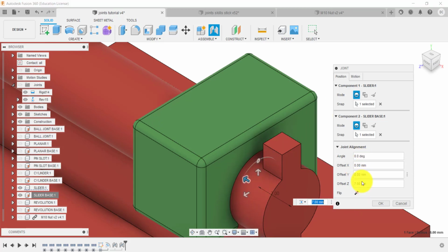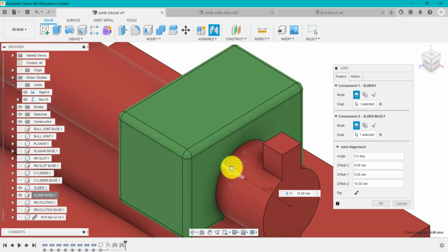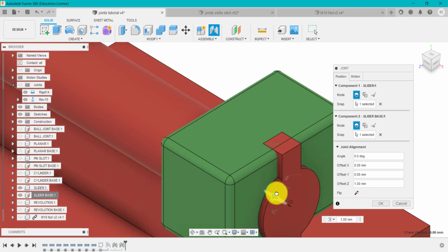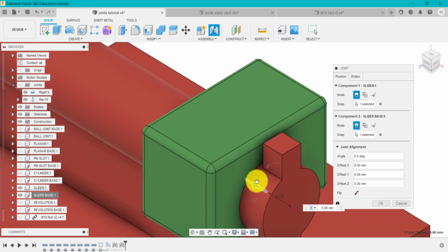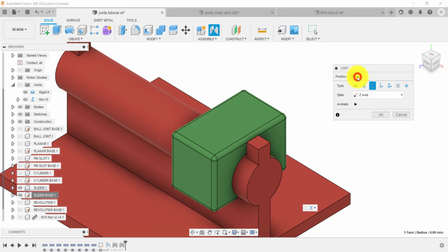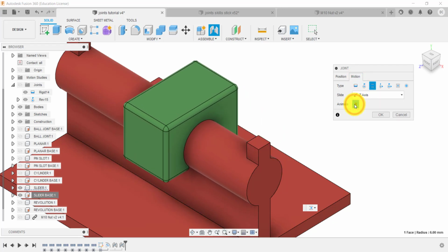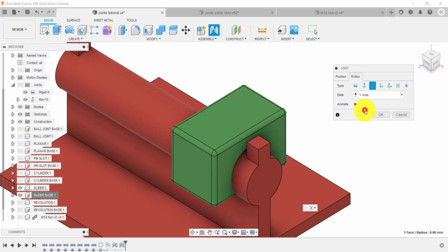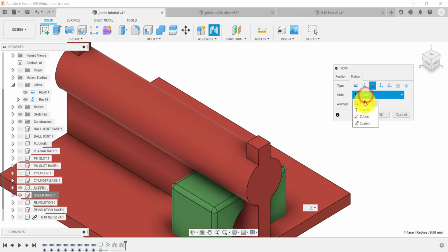So this is where you can change your alignments. Later we will tell it a certain limit so it's not going to go through here as well, but I'm just going to move that, say, up 5mm. Just going to go into motion just to check it's correct. There you go. So I haven't selected the wrong axis, for example.